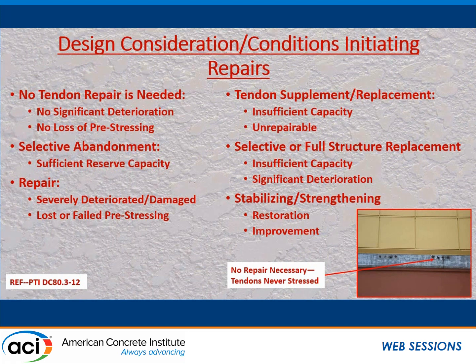And so we're running around, and of course there's rigid insulation on the underside, and you can't tear it all out. There's all this mechanical, and we go to the other end, and we find these things, and we open up the dead end anchors, and we don't see any distress there. We're trying to figure out what to do, so we finally say, well, we're going to go up and put a stressing ram on it and just see if we can extract it. And then when you pull it out, if it's 40 feet long, then 40 feet in, that's where your break is. Put a stressing ram on it, went right up, it pressured up, in a short period of time,